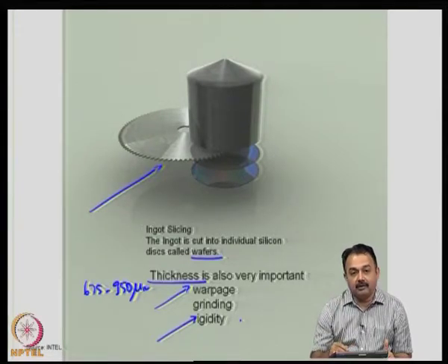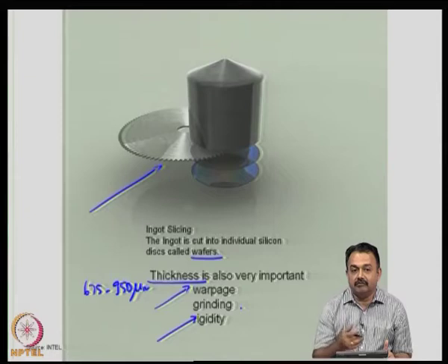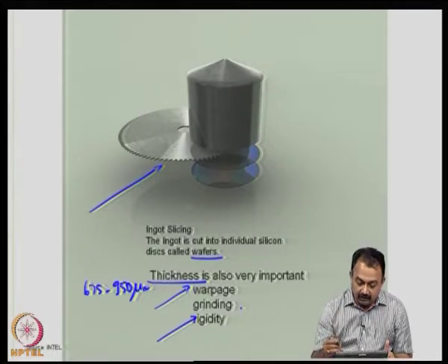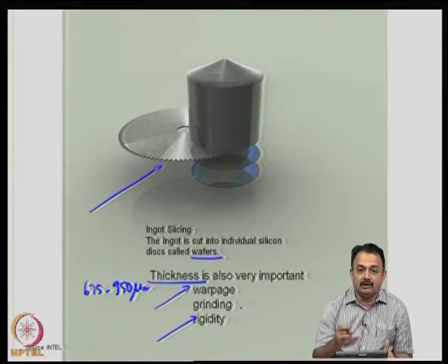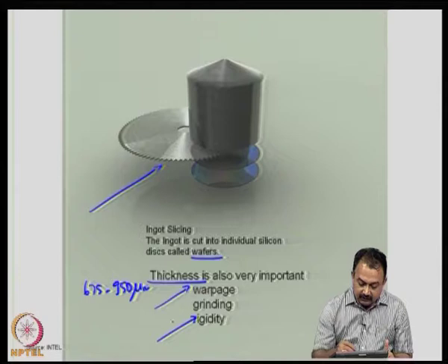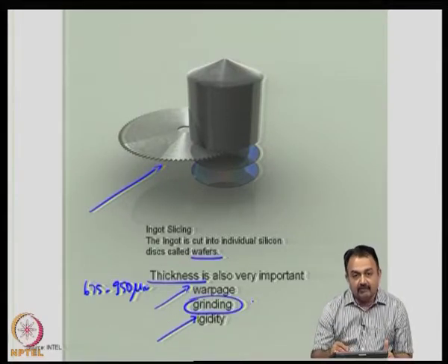All of these are very important for the process, because the wafers in lots of 25 will go through various chemical and mechanical processes. So, they have to withstand the chemicals, and various rinsing processes are going to be present during the cycle. Now, as I said earlier, grinding will take place finally after the entire process is completed, to reduce it to the required thickness of the die.